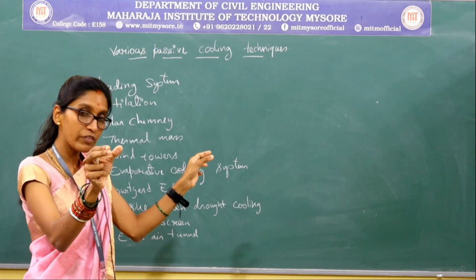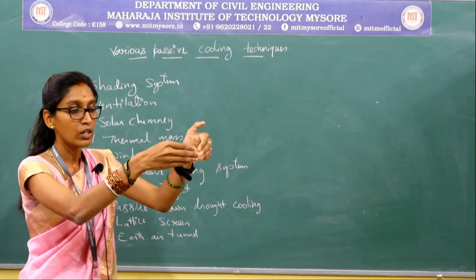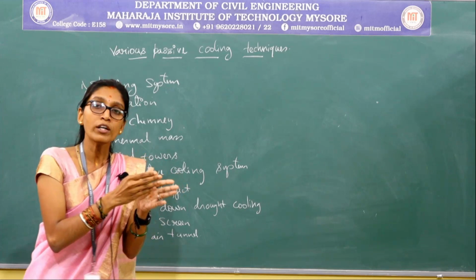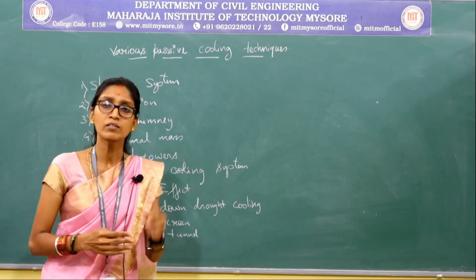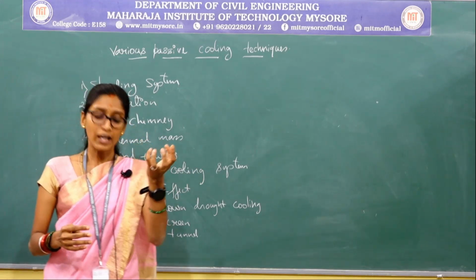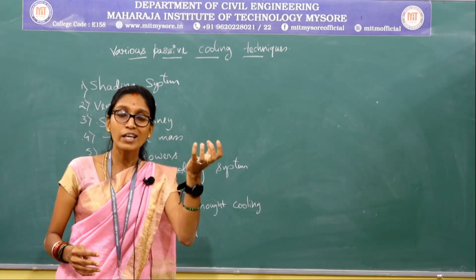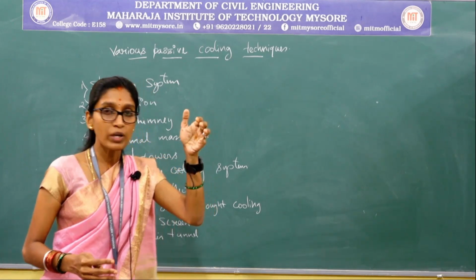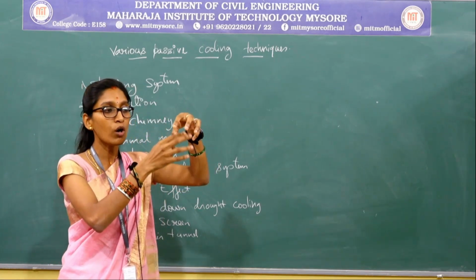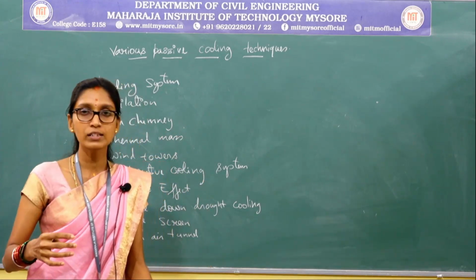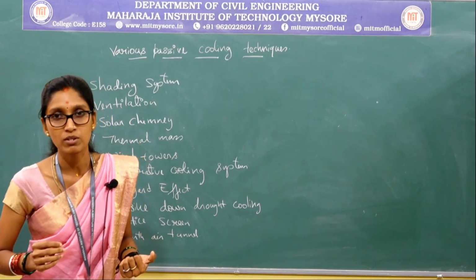When these towers are being lifted with the hot air, the downdraft of the cool air will be happening from your downdraft tower. So what is the phenomenon taking place here? These downdraft towers are installed with a wet cellulose pad, and the water coming out of those cellulose pads will be collected in a sump, and then the water will be recirculated using the pumps, okay.